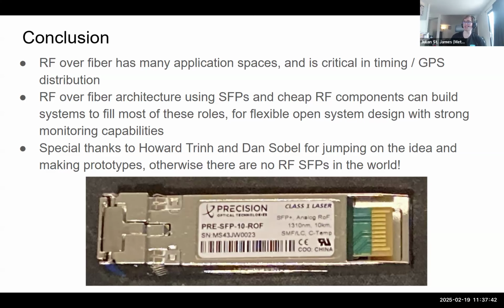Yeah, I wouldn't want to put too much into the SFP, right? It's a building block to get you to play with the optical domain. Once you have that building block, then you can put a lot onto the board side or the host side to do whatever you want to do. So I think this was perfect for what I was looking for. Something I didn't mention, I guess I could have added, was when I talked to you guys about this, you said the laser itself is an independent subsystem inside the transceiver, right? Like you said, you can put a DWDM, CWDM, BiDi or whatever. So cool. All right. Thanks, Mike.